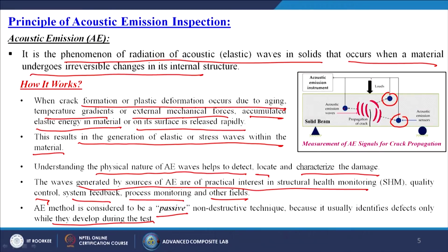So, we have the acoustic emission instrument over here. We are giving the waves over there, and we have the sensors at different locations. We are giving the load and it is acting as a double cantilever beam type. So, simply, if there are any breaks or cracks, or if crack propagation takes place, the sensor will sense that sound and give it to us.